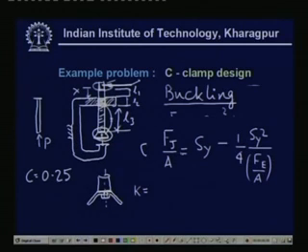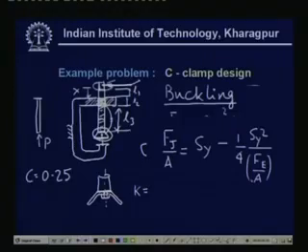We have to use this formula in order to check whether the given load is more or less than F_J, once we have decided on the diameter, the core diameter. Definitely, if the load is more than F_J, then we will have to increase the diameter by some amount, and then again we have to check this formula. Now, this is about the buckling.